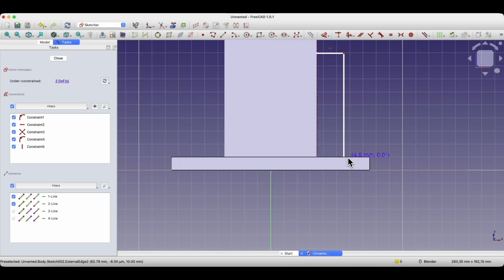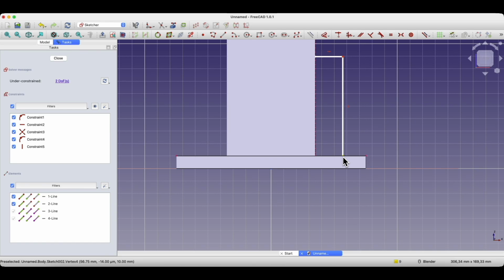If you are not sure whether constraints were added, right-click to finish the polyline and again to cancel the command. And drag the last point, and you will see it's constrained to the line, which is what we want. If the constraint wasn't applied, we could add it manually.